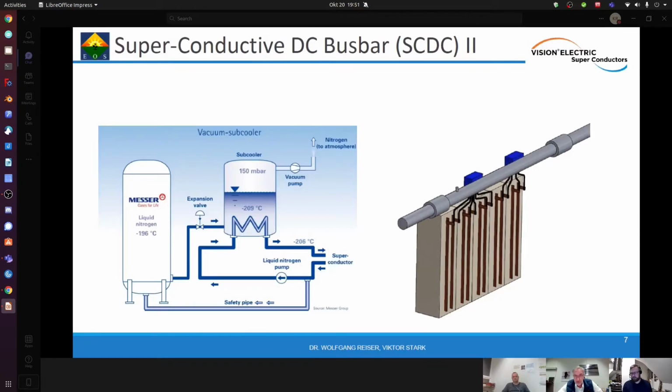And then we have a DC converter, which is very efficient because we only convert DC to DC. We convert 500 volt, for example, or any other voltage which is coming out of the battery, to 48 volt DC or any voltage which is required on the OCP rack, or we convert to 24 volt or whatever.